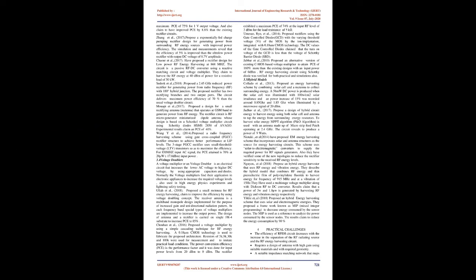The RF to DC conversion module uses a 7-stage voltage doubler circuit. Ipar et al., 2016, proposed an energy harvesting scheme using a microstrip patch antenna that operates at 2.4 GHz. The proposed RF energy harvesting technique is implemented for many electronic devices like LED, scientific calculator and battery charging. The RF method designed is reviewed using simulation and practical experiments.